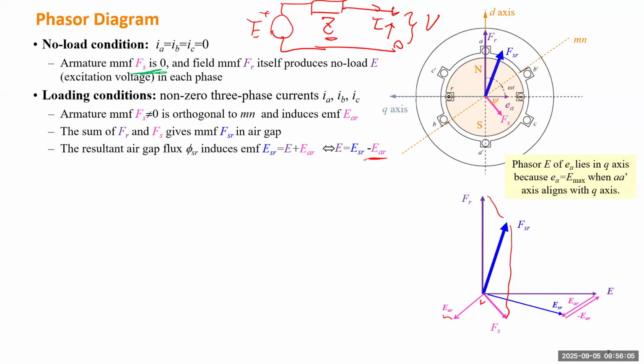So we create another phasor opposite to the armature winding induced voltage, because we want to interpret this E as the terminal voltage plus some voltage drop inside of the generator. Then we draw the current in the same direction. Then we define a reactance. The reactance will try to interpret what happened here: the voltage drop inside of the generator is because of the current through some reactance.